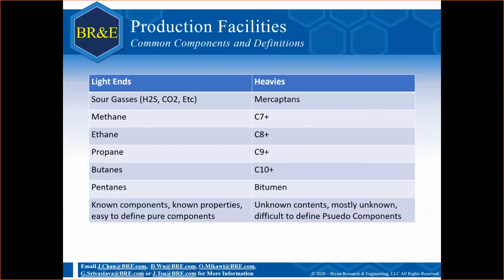ProMax allows us to add these components into our system as single oils, or oils in general. There are two types of oils, which we'll discuss in a minute, but they'll be added in as oils. So pseudocomponents can be added in as oils, and pure components exist naturally in our ProMax environment, and we can simply take that information from the environment.